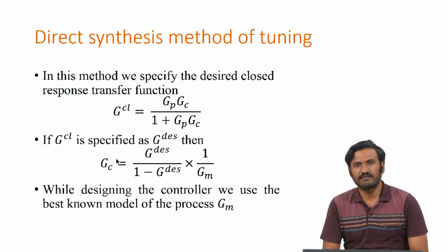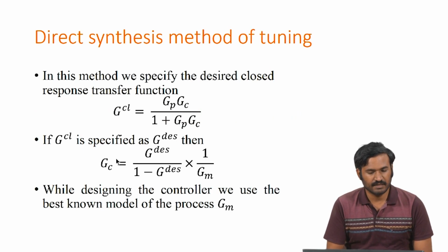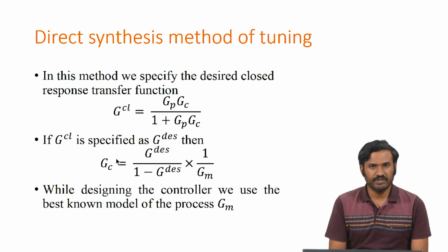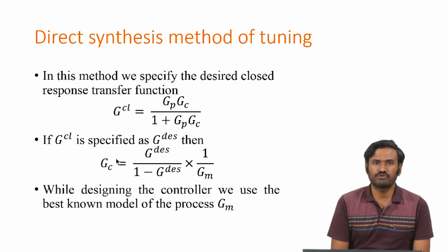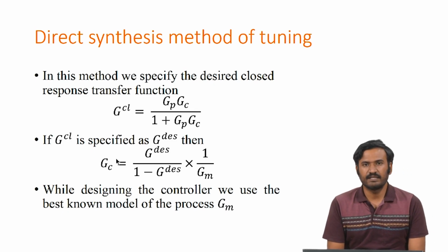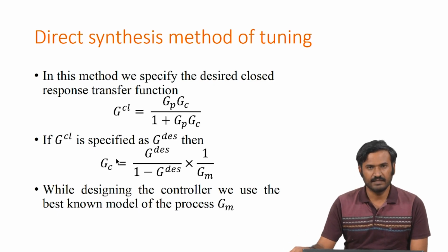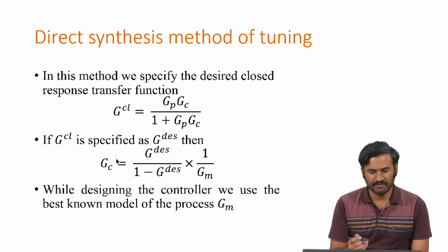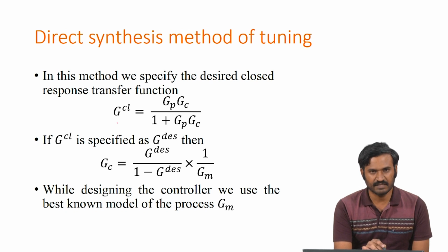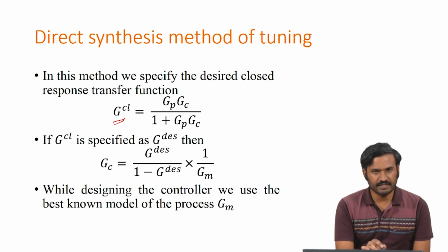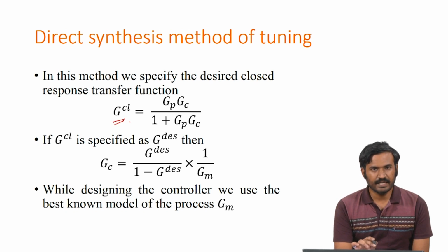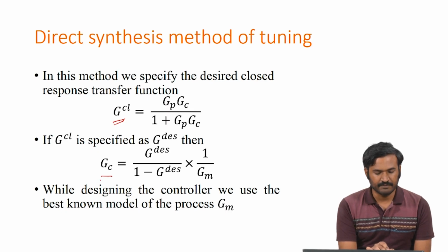In this method we have direct synthesis method of tuning, where we specify the required closed loop performance in terms of GCL. As can be seen in the closed loop transfer function, we can specify GCL and ultimately back out GC.